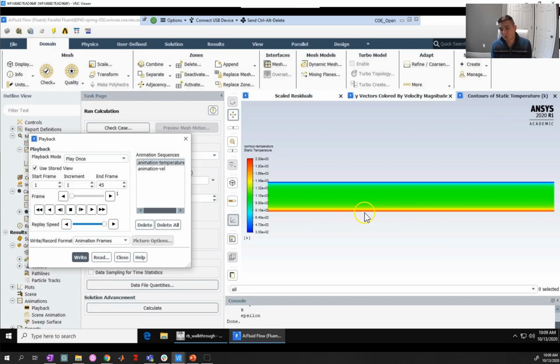And so what's going on is we're heating a system filled with air, where we're heating on the bottom and cooling on the top. Because the fluid at the bottom of the domain is heated, the density decreases, whereas the fluid at the top of the domain is cooled, so there the density increases. Now you have this instability, with higher density fluid at the top and lower density fluid at the bottom, and because we've turned gravity on in this system, you're going to create what are called convection cells. So the hot air will rise, the cool air will fall, and we'll get these overturnings because we're constantly cooling at the top and heating at the bottom.